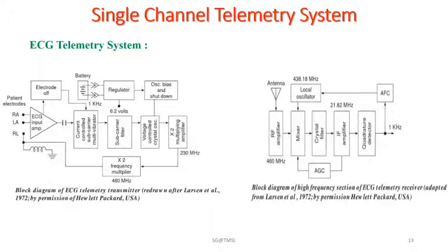It provides low noise figure, RF filtering, and image frequency rejection. Then a local oscillator circuit is there, basically 115 megahertz, which is to be multiplied by 4. A multiplier circuit can be used, and a tuned amplifier must be incorporated here.